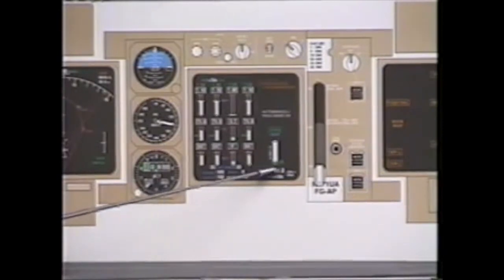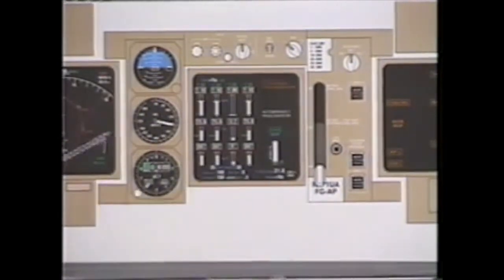Total fuel value, standard fuel density, the maximum fuel weight you can cram in the airplane is 388.7 thousand pounds. Fuel temperature is displayed, and if you have engines or ECS selected on the lower or secondary ICAS, you have ECS information as a result, showing duct pressure in both the left and right wing manifolds, the current cabin altitude, the landing altitude, the differential pressure, and the climb or descent rate.